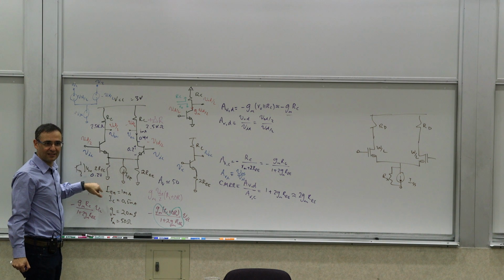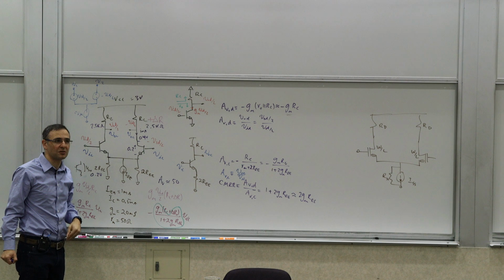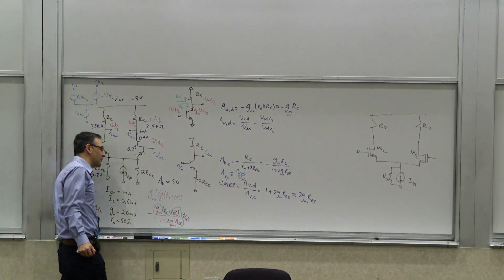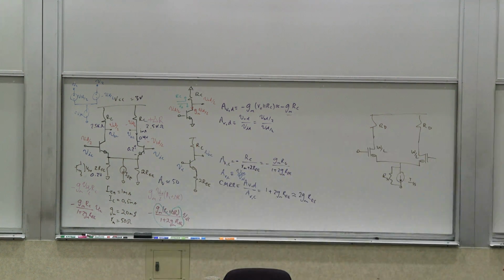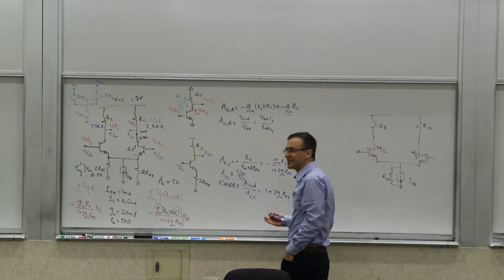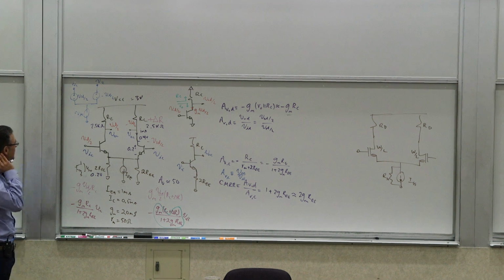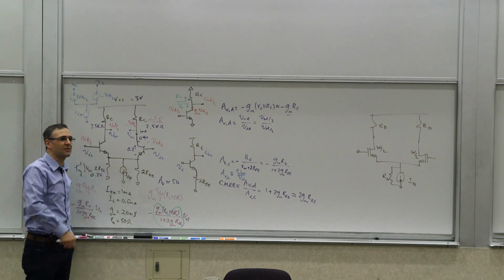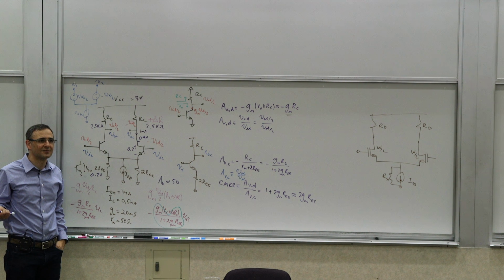Now, I don't have an ideal current source, so I can't basically just go below that. So what it means is that if I put 10 kilo ohms here, this transistor will go into saturation. So it's not going to be operating properly. You put it in SPICE, you expect a gain of 50 or 100, you see a gain of 0.1. That's what's happening. The transistor is not really operating in the proper ranges of operation. So it seems like a dilemma, but you may say, okay, wait, how about you make this 4 times larger, make it 10 kilo ohms, but make this current 4 times smaller. That way, the DC will work out, right? Right? Do I get more gain?